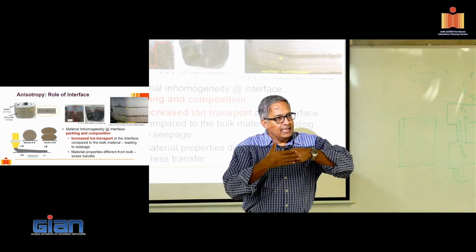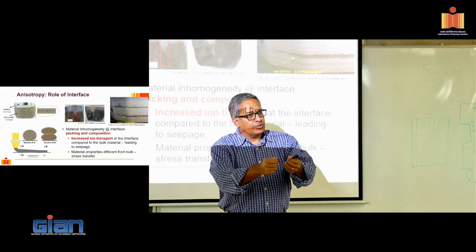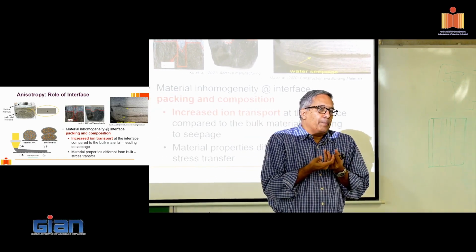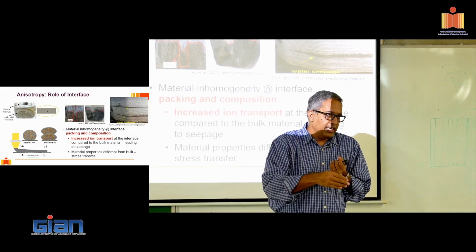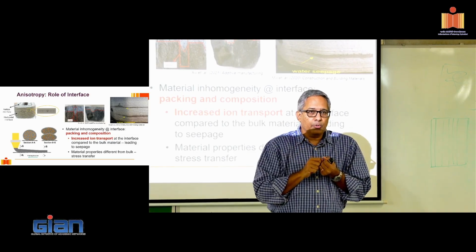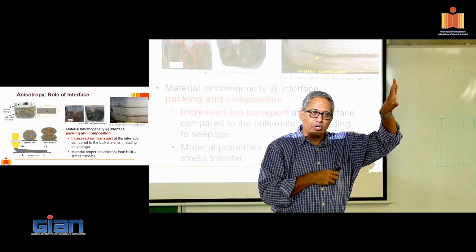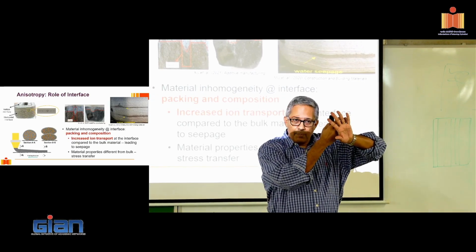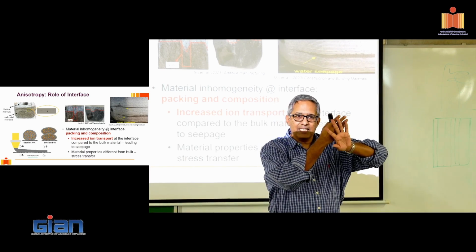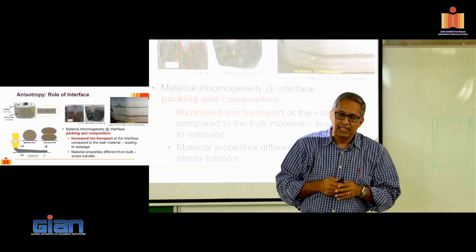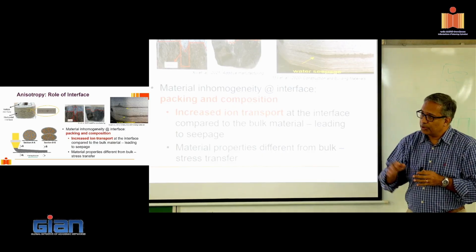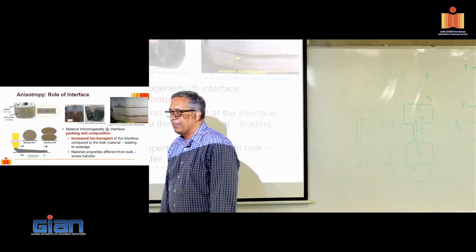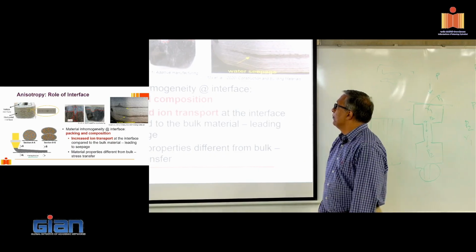So how does a bond develop when you place fresh concrete against an old concrete? At some level, we expect that the cement paste from the fresh concrete perhaps penetrates into the porous structure of the old concrete, and that's where the bond is developing. So perhaps there is some chemical bonding that's happening, and there's also some physical bonding that may be happening where the paste from the new concrete penetrates into the pore structure. But at this point, we still don't completely understand what's happening at the interface, but an interface forms.